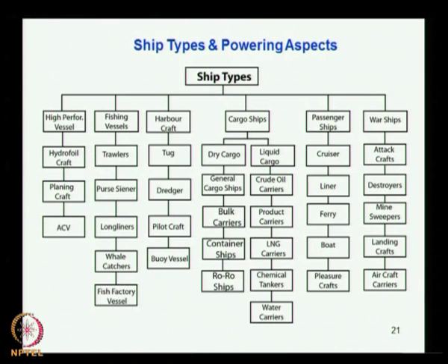While doing so, there are two aspects. One is the resistance offered by the fishing vessel, and the other is the resistance offered by the net with the fish inside. So it is a different operating condition. Whenever you do resistance estimation or power estimation for fishing trawlers, it has to be done for two cases, that is the free running condition and also the trawling condition. And also on the return trip, it is now loaded more, so the displacement is more, and you have to look into that aspect also.